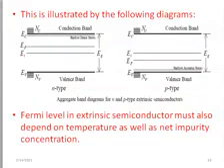And this is illustrated in this diagram where we said Ef for the n-type is above the Ei. Look at the diagram. This is my Ei, the intrinsic Fermi energy, and this is my real extrinsic Fermi energy, Ef. It is above what? This, based on the equation I've just discussed. But in the case of p-type, we see Ef is less than Ei, therefore you see it below the bar.